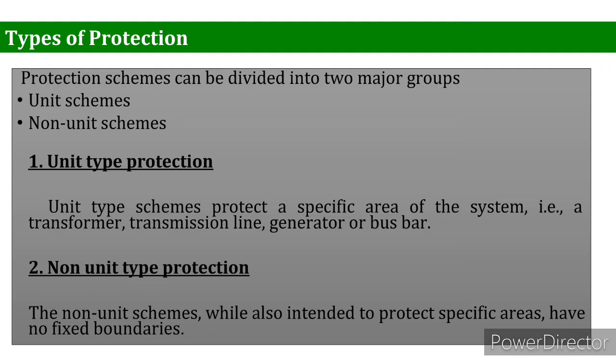In these schemes, the effects of any disturbance or operating condition outside the area of interest are totally ignored, and the protection must be designed to be stable above the maximum possible fault current that could flow through the protected area.